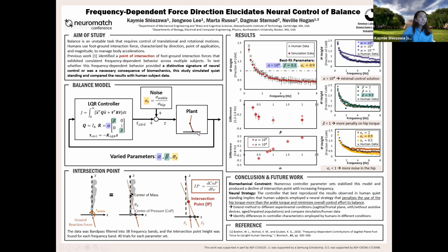Although I used a nonlinear plant here, and then just applied a linear controller. And we also saw that when simulating, the center of mass did not change its height very much. So that also speaks to how much the pendulum deviates about the upright position. It doesn't really deviate about the upright position, basically.